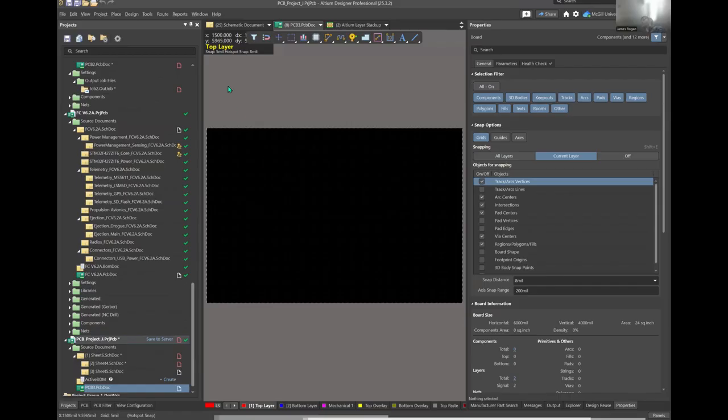So there are three things I would do before I start any component placement or routing, which is to set up the document. This involves defining a board outline, so you have rough dimensions based on some requirement from a mechanical person, and you put that on there. You would define your design rules so that Altium knows what to warn you about. And you'd also define something called your layer stackup. I'll go through those three things just because I think they're important, and it will save you time in figuring this out if I go through them now.